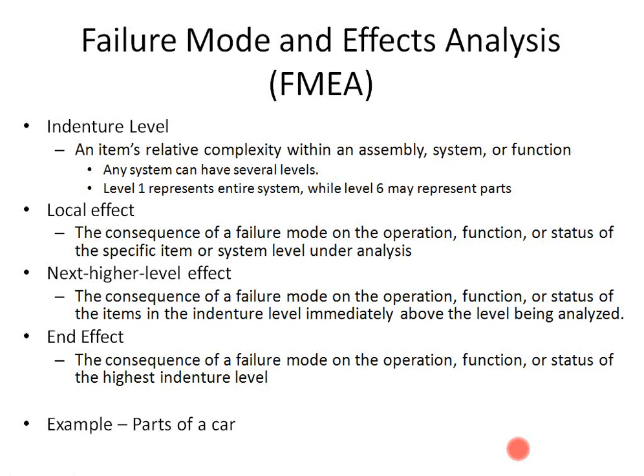This goes actually into a lot more detail than it had in the past, which I think is good, because it talks about indenture level, which is an item's relative complexity within an assembly, system, or function. And so you can have a level 1, you can have as many levels, even 20 levels. But the idea is level 1 is going to be the entire system. And we'll use a car for an example later on.